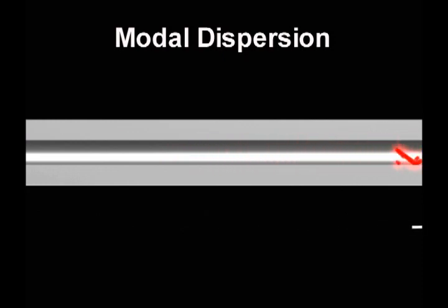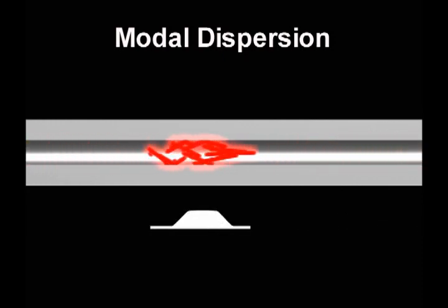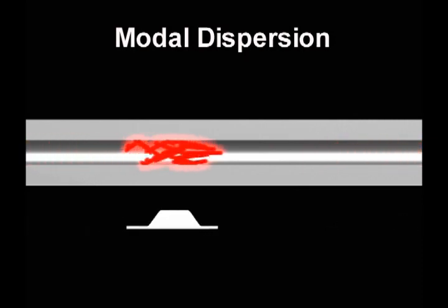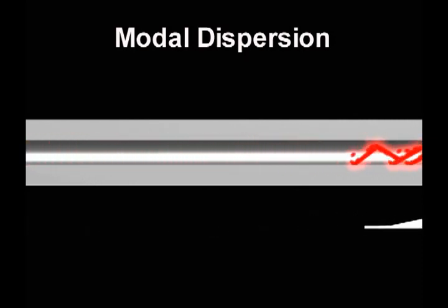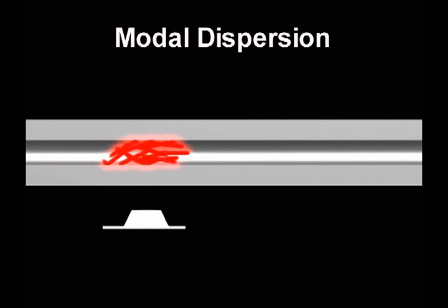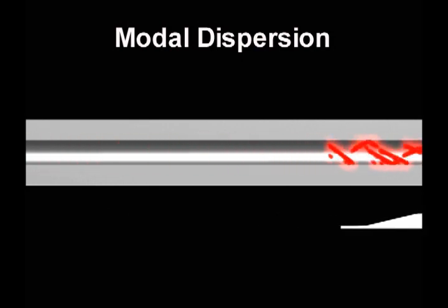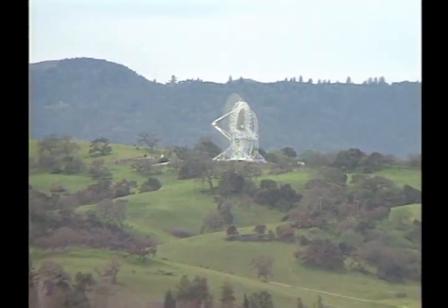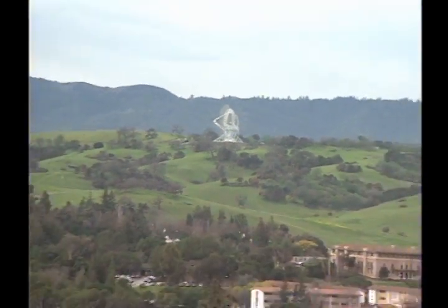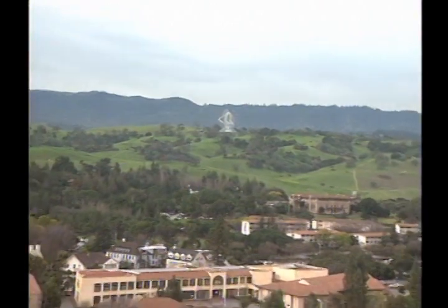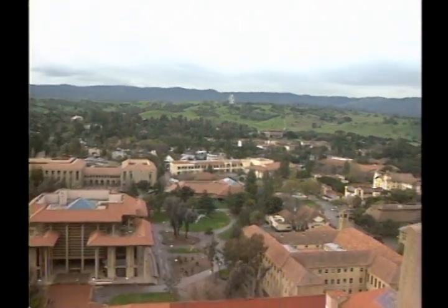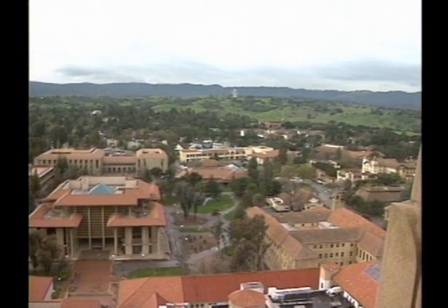This has the effect of stretching the optical pulse, which is called modal dispersion. This effect limits the usefulness of the fiber at high transmission rates when pulses begin to overlap and garble the information carried. The degrading effect of modal dispersion increases with fiber distance, so for this reason, single-mode fiber is the preferred choice for long-distance, high-bit rate transmissions, as it is not affected by modal dispersion.